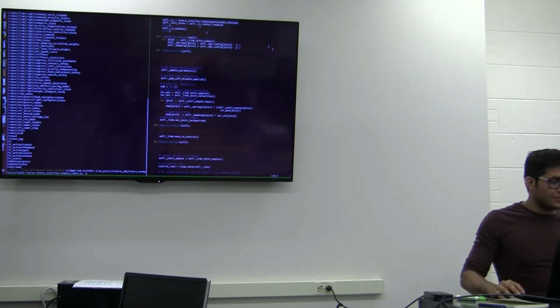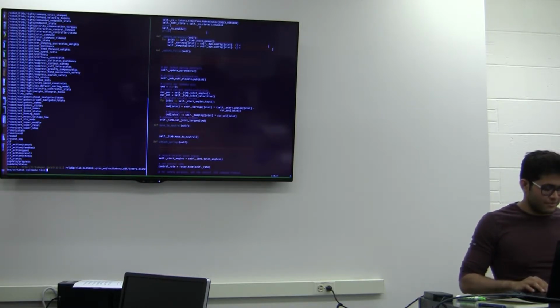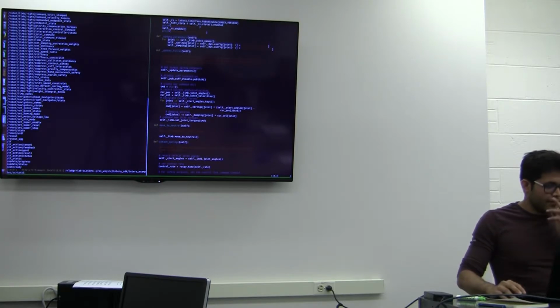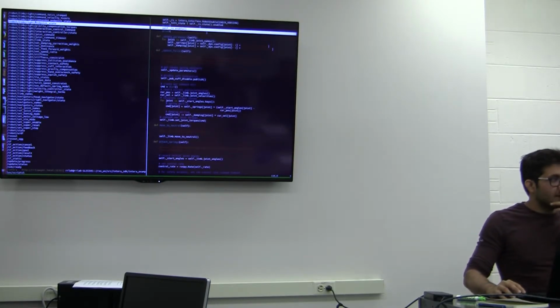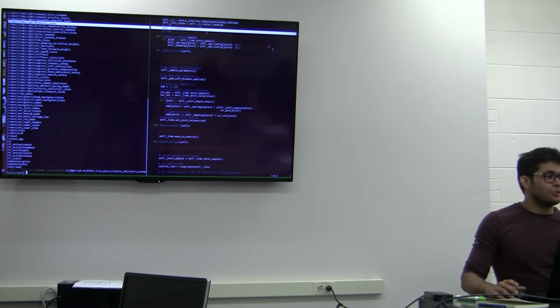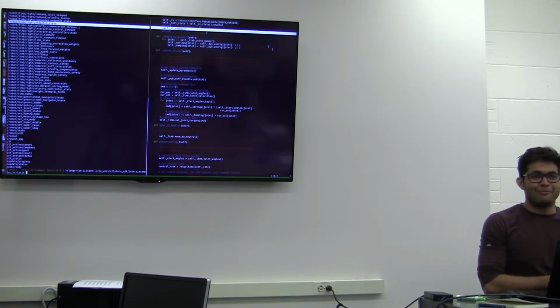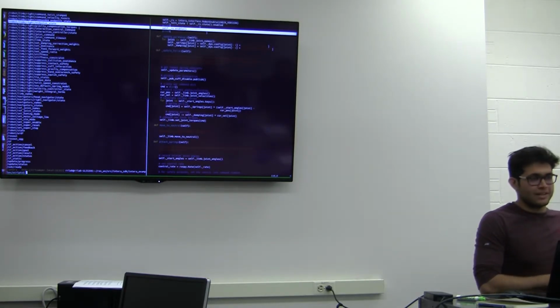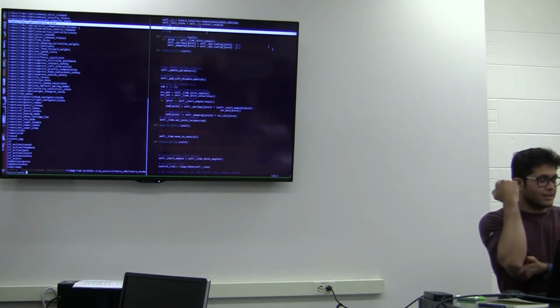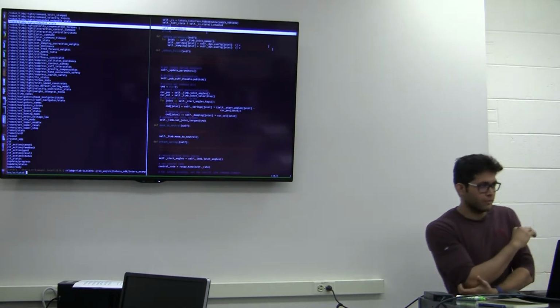Basically you can give endpoint state to the robot. So in other words, we don't want to compute inverse kinematics. Why do you want to do that? That's the whole purpose of using ROS, because you don't want to create the kinematic model of the robot again. It's already been done by the company, just use that. All their topics are using those functions, so you don't need to worry about that.